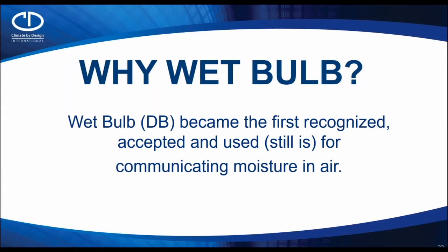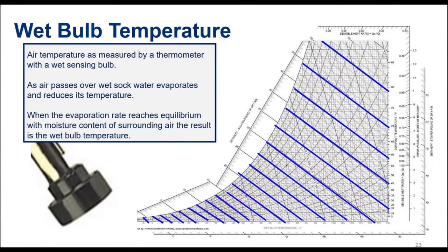Quite often when we're looking at a cooling coil program or something like that, we're going to be asked for a dry bulb and a wet bulb condition. Wet bulb lines are diagonal lines on your psychrometric chart. These wet bulb lines, and I'm going to help you just a little bit, I'm going to zoom in.